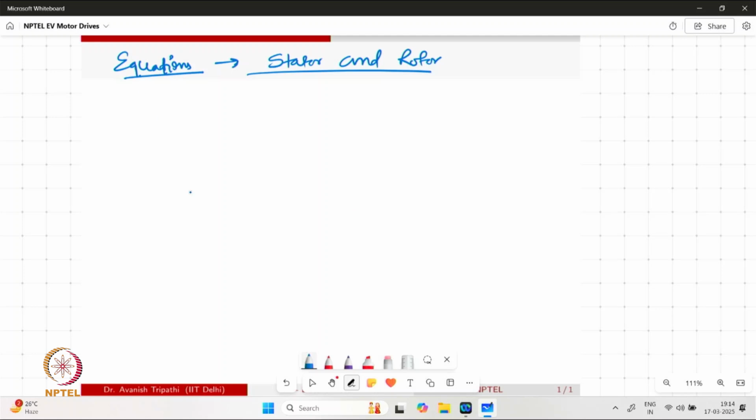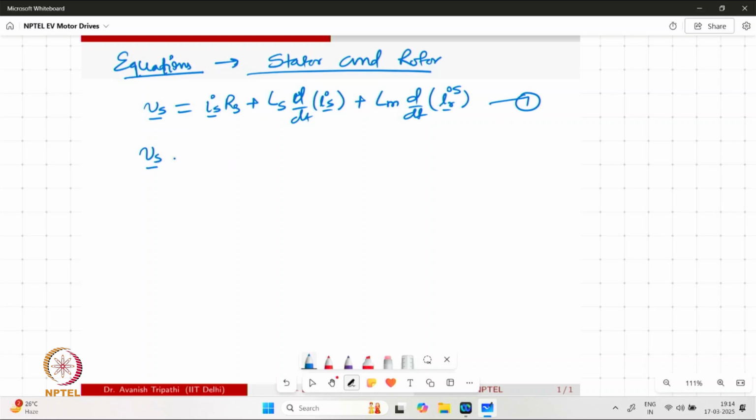So what we have understood is that for the symmetrical machine, we are writing the stator and rotor KVL in the native frames of reference, and we can define the quantities which are appearing from a different frame of reference by having a superscript.